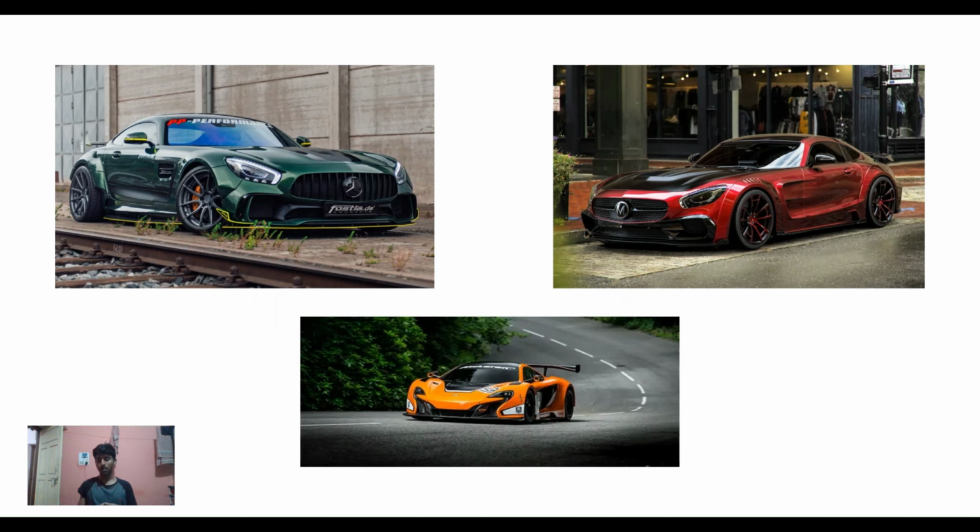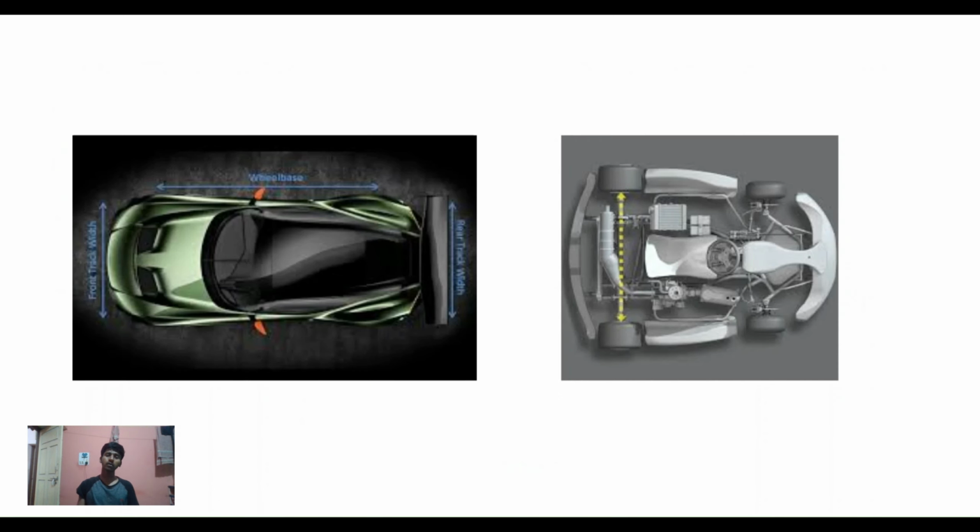My suggestion is take as wide a space as possible, because that will always help. In track width, it's not necessary that the front and rear track width will always remain the same. In most cars, you always see that front and rear have almost the same dimensions. Even if they're different, you can't generally make them out. But say you're doing top speeds, or very tight turns at top speeds, that time you need to have wider track widths.